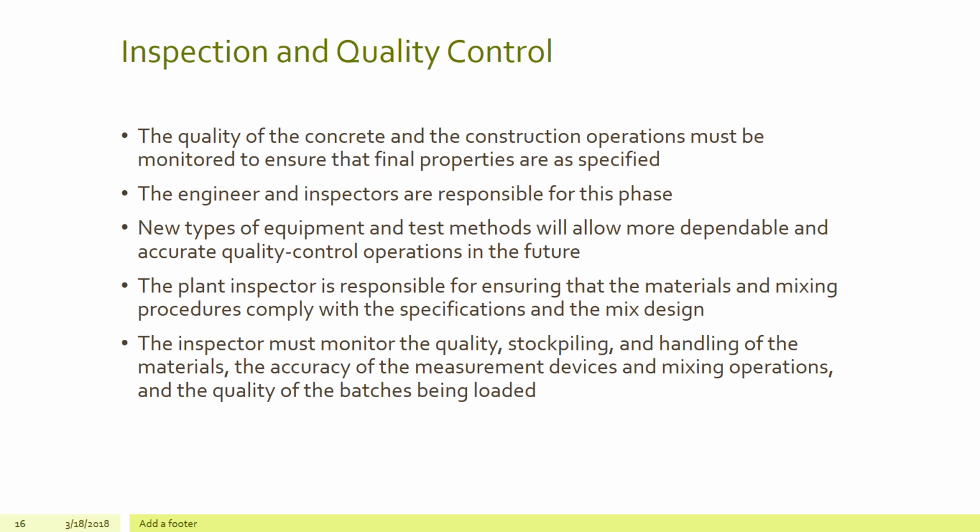The plant inspector is responsible for ensuring that the materials and the mixing procedures comply with the design specifications of the mix. The inspector must monitor the quality, stockpiling, and handling of the materials, the accuracy of the measurement devices and mixing operation, and the quality of the batches being loaded.